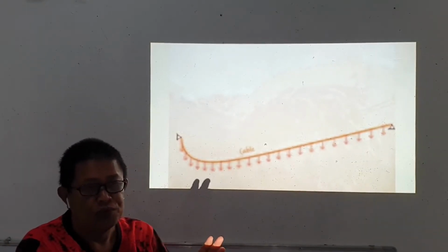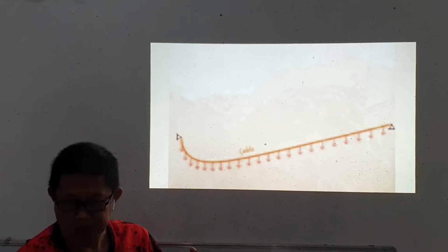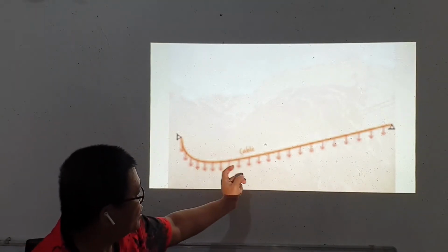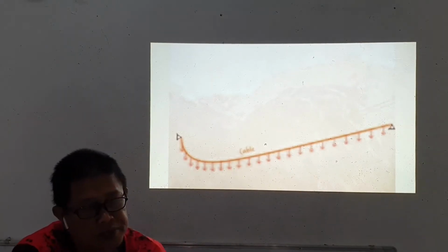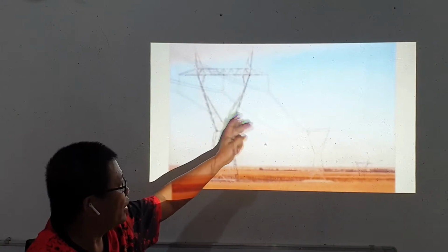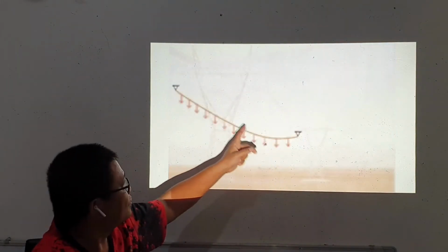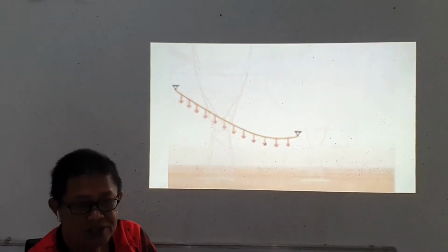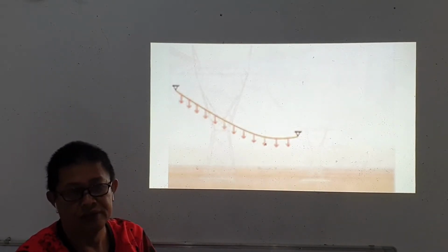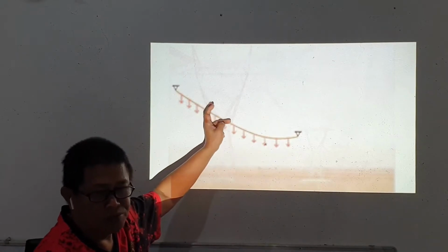It is computed from the application of the distributed load along its horizontal span, while for pedestrian bridges, the loading is distributed along the actual length of the cable. So this is how we analyze cables used for pedestrian bridges. This is also similar to cables for electric wiring, electric cables, also being supported by towers. So the distribution of the load is also similar to the pedestrian bridges, in that the load is significantly taken from the live load of the cable, and it is distributed along the length of the cable, which follows either a parabolic or whatever curve is followed by the cable.